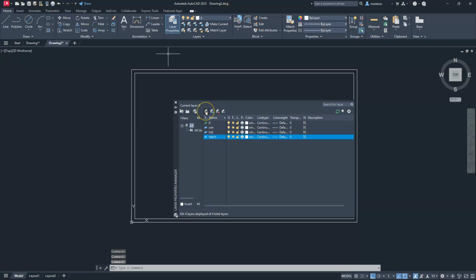We can also use a phantom layer if you want, or something for a section. That's going to be totally up to you if you want to do that. We can create a text layer, but we do need one more at a minimum, which is going to be the dimension layer, right? I always like to create a dimension, a hidden, and a center. So those are going to be at least the 3 ones that you should create on each one of your drawings.